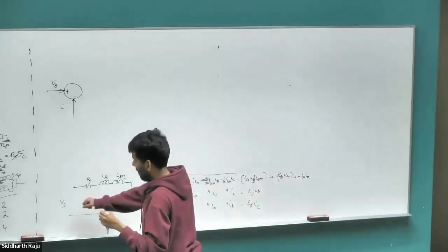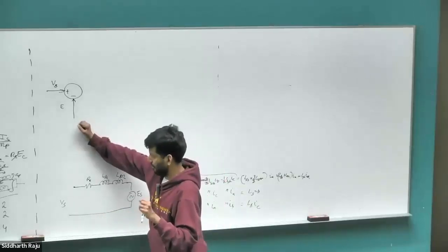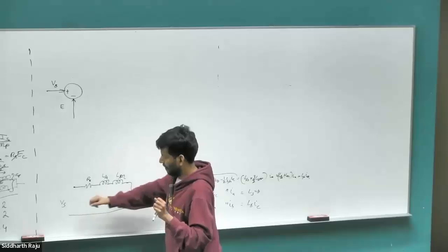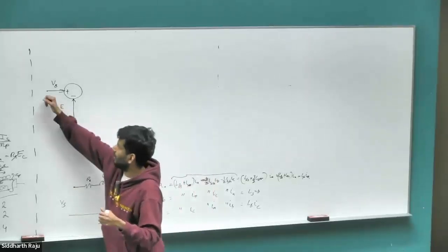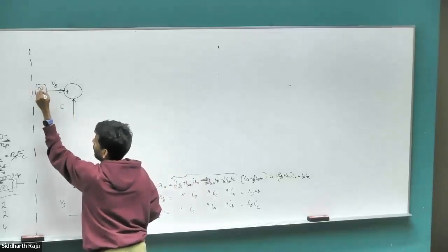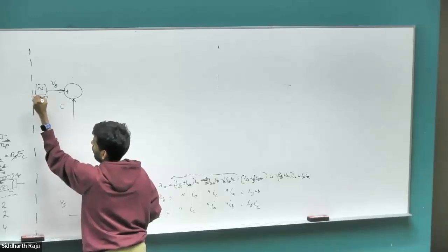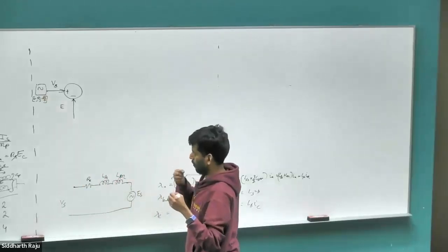Okay, so we have our terminal voltage. We subtract our back EMF. We don't know how we'll get this back EMF just yet, but just leave it hanging. The terminal voltage is given to us by 3 sinusoidal voltage sources, and we will put those 3 values here. Take a sine wave in MATLAB, with the angles phase shifted by 0, 2 pi by 3, minus 2 pi by 3, minus 4 pi by 3, and put some magnitude for the voltage.